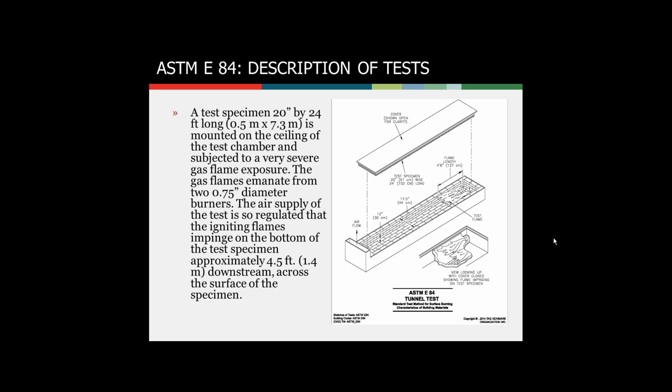Okay, and could you please explain the leaching process? The leaching process is 72 hours where you use filtered water, very clean water, that is put into a large container, at least 15.1 liters. You would put the material into the container and fill it up. The water that goes into the container has to be at 20 degrees centigrade.